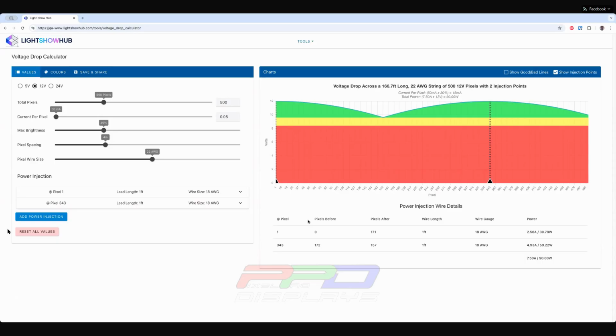A default of 0.06 or 0.05 on this produces so many questions. Folks need 6 power supplies on a tree that only needs 2. Yeah. So Steve, like I said, the actual current per pixel, I haven't tested them in years, and I know the current is much lower than it used to be. So I do not know what the default is, but I would say most common for new bullet pixels, whatever the most common current per light is at full brightness, full white.